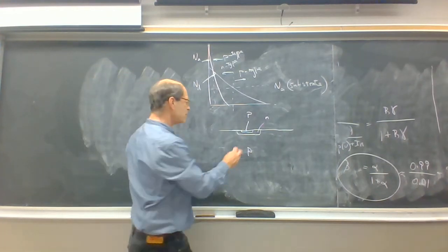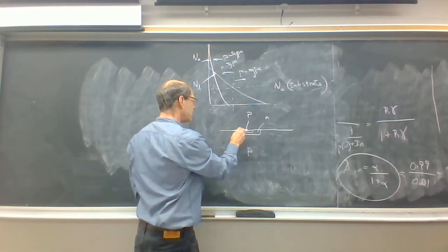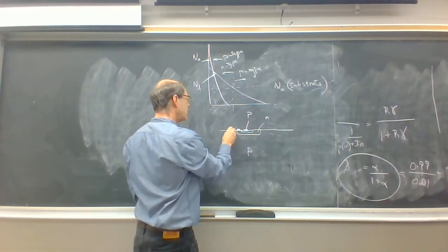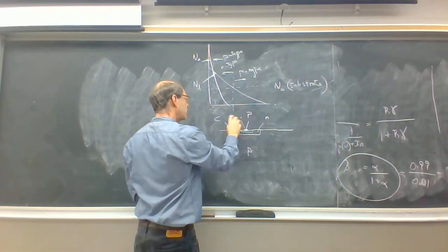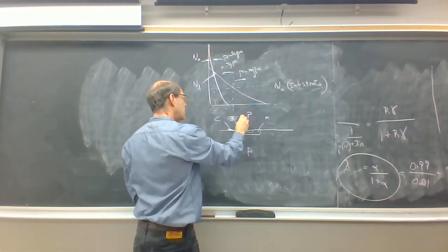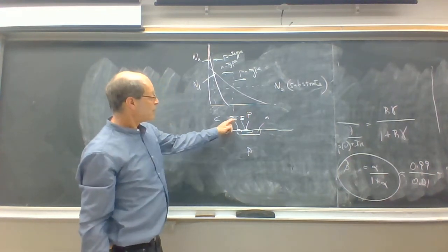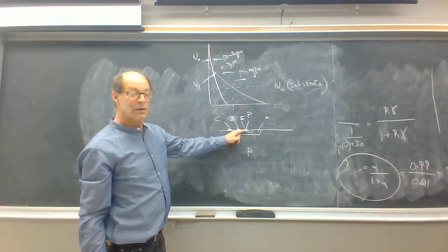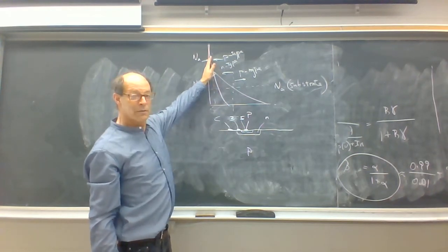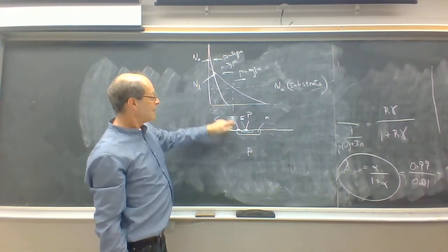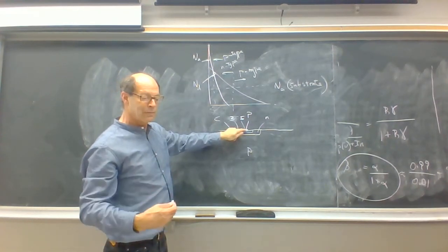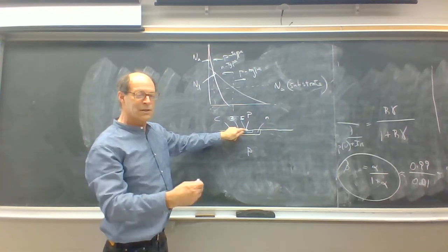So now with this structure you can put electrical contacts onto these three regions, which become the collector, the base, and the emitter. And you can see that the emitter is naturally going to be heavily doped, which is what we want because it's right near the surface of the transistor. And that gives you the high emitter injection efficiency.